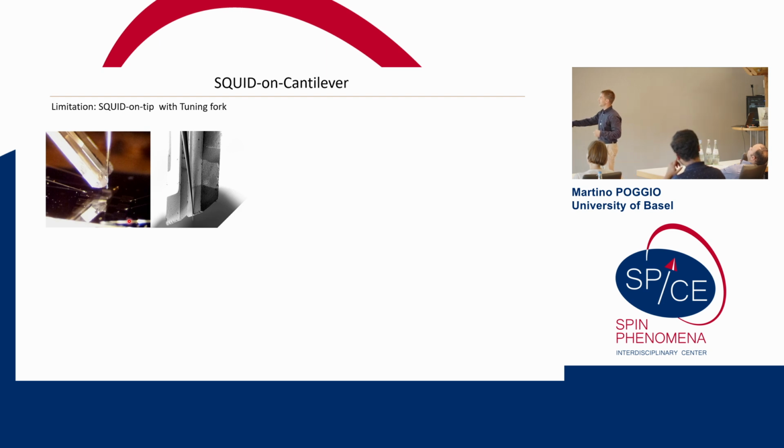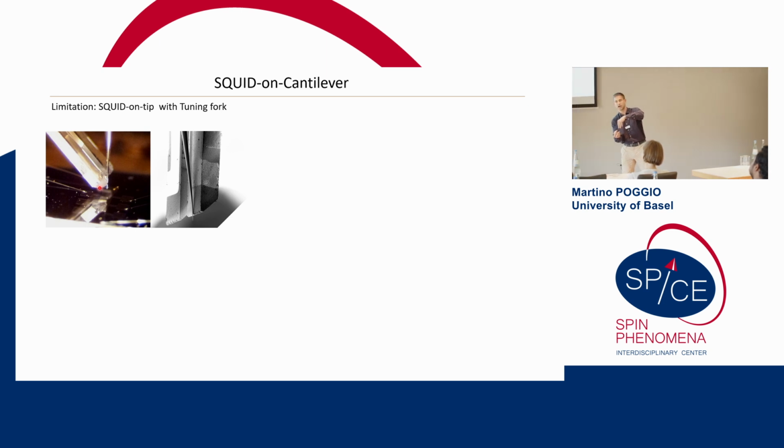So you can imagine, I try to hit it home by this picture that you see here. This is basically just a glass needle with a 50 nanometer tip that you have to bring 50 nanometers close to a sample and scan it around for multiple days, right, without touching. And that's a big problem. So the usual way that people doing scanning probes solve this is they couple these fragile probes to some kind of mechanical oscillator, and so then when it comes very close, there are some kind of interactions between the surface and the tip, so electrostatic or van der Waals, and these forces essentially slightly change the mechanical resonance of this mechanical object, and then you can detect before you make a touch, before you crash.